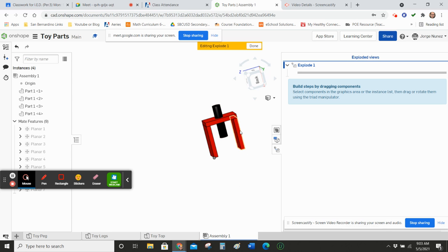We also know that the legs are individual legs for the right side and the left side. They're not connected to the tabletop, so it's not like an L connected to an I-beam on the left side, or vice versa, not like an L on the left side with a stick on the right side. So it's basically three separate parts that make up that tabletop. We need to say that, and the way that we can say that is through an exploded view.